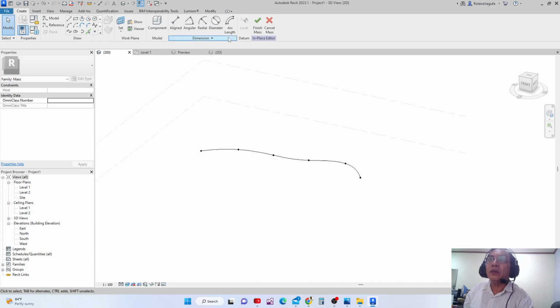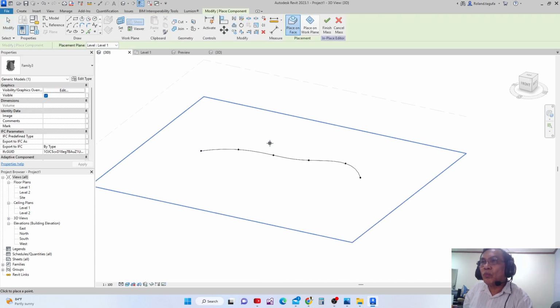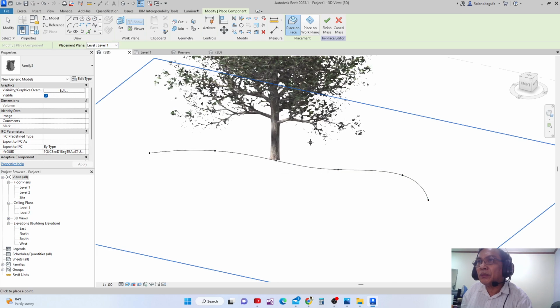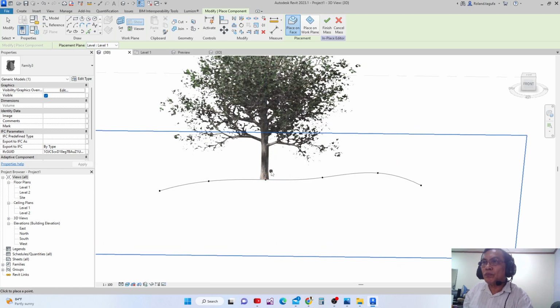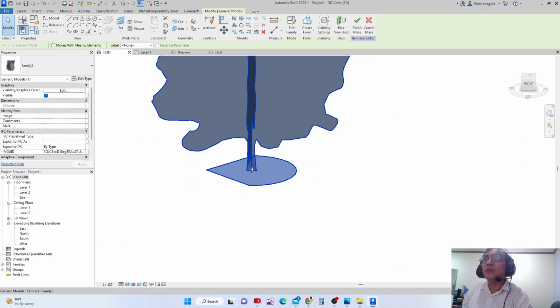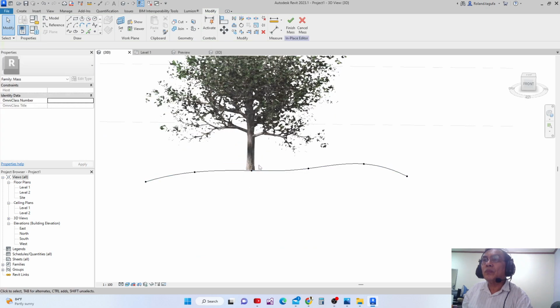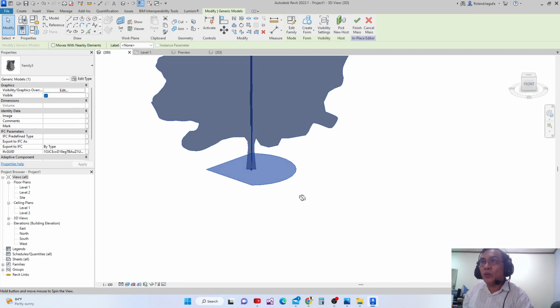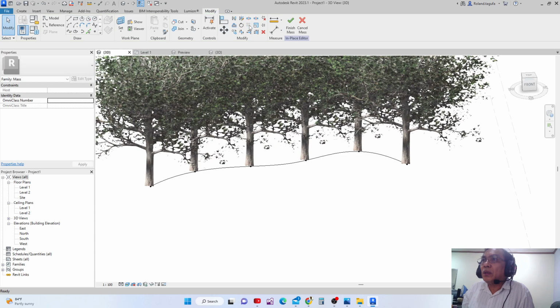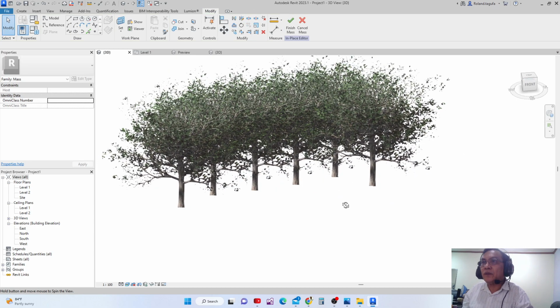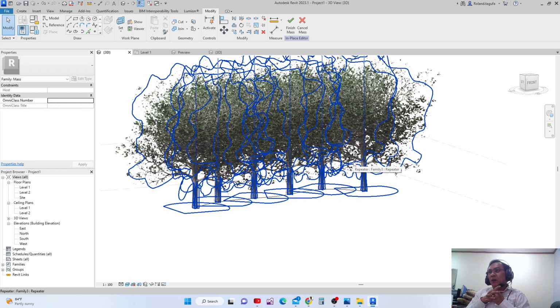Again go to create, and then just touch this point, and then you select it. And then when you select it, there is already an option of repeat, and I can repeat it, and I can make it there in every point. Now it's already there in the point. That's the difference between doing an adaptive component and a generic component.